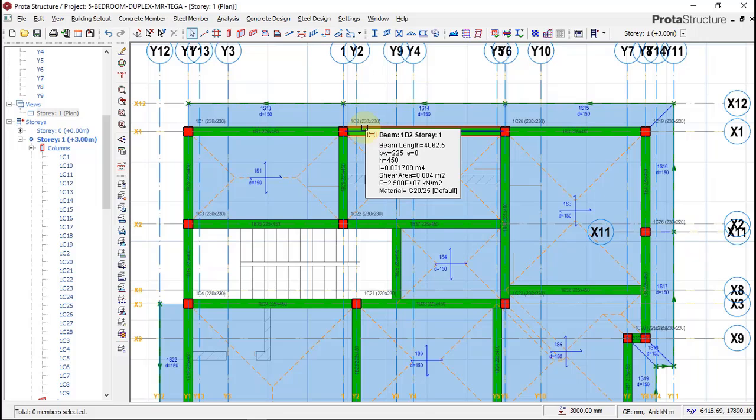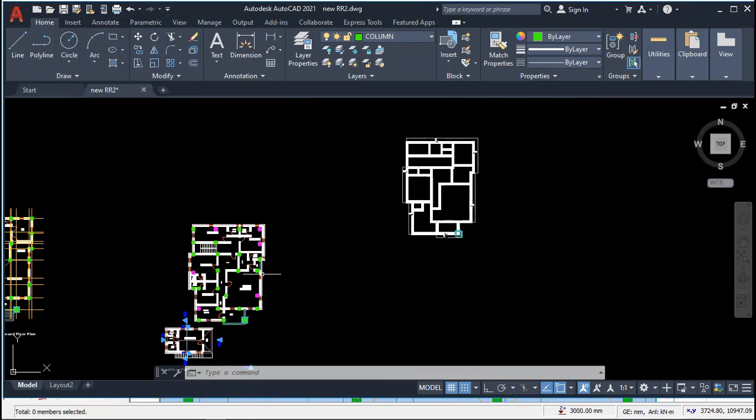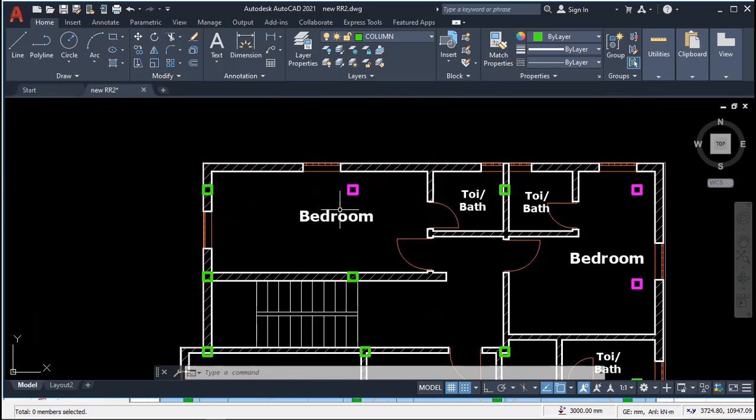Okay, after creating our cantilever slab, the next thing we will have to do is to insert Storey. Looking at this, we only have one story upward. Because of our cantilever, when we insert our Storey 1, the first floor, some of the columns will be terminated on the ground floor. So we will have to delete and shift this column from this area down to this area.